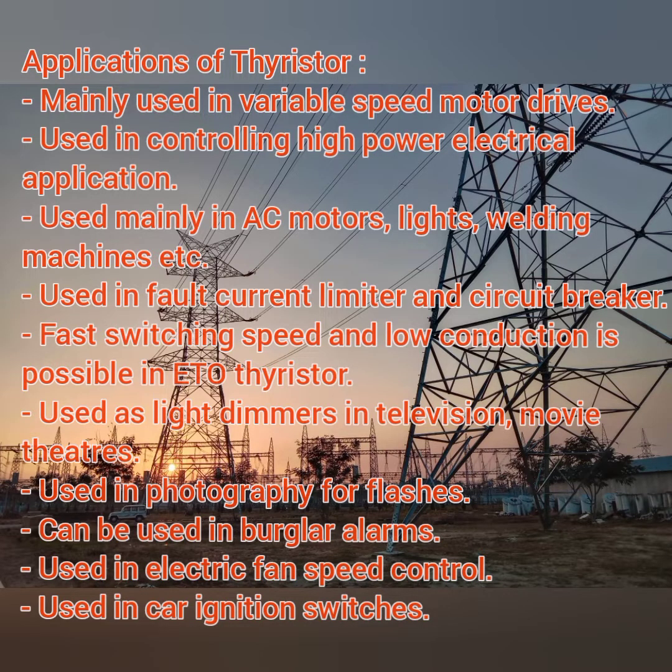Next, coming to the applications of thyristors. Mainly it is used in variable speed motor drives. Then it is used for controlling high power electrical applications. Then used mainly in AC motors, lightings and welding machines. Then used in fault current limiters and circuit breakers. Fast switching speeds and low conduction loss are possible in the ETO type of thyristors.